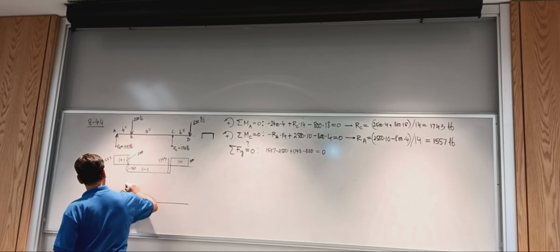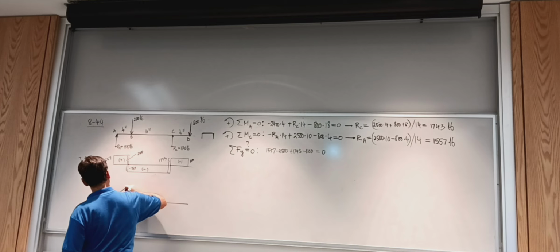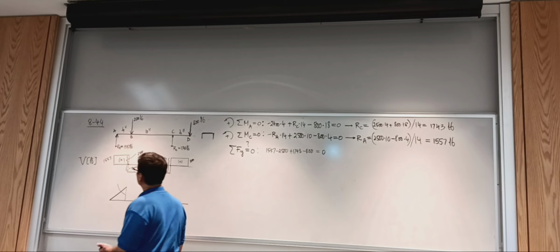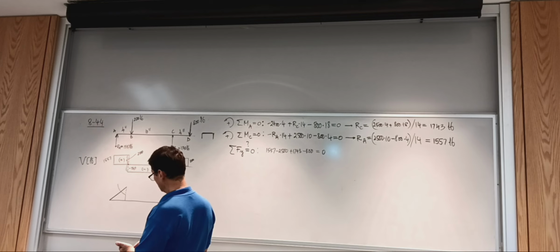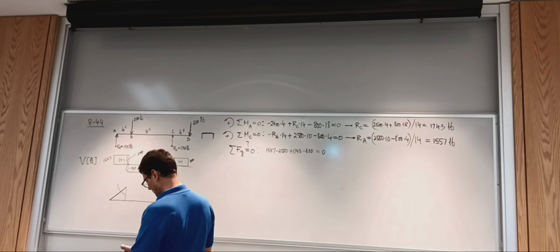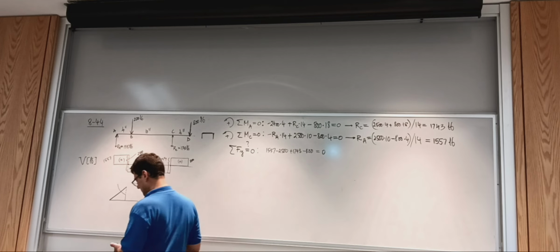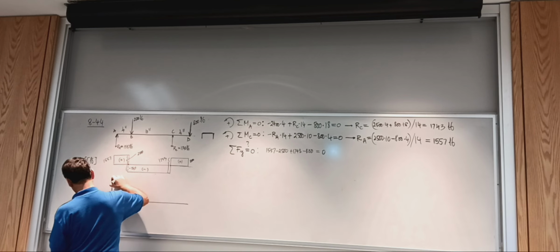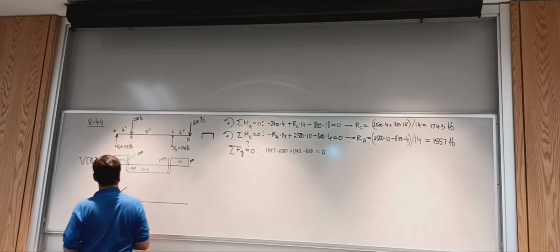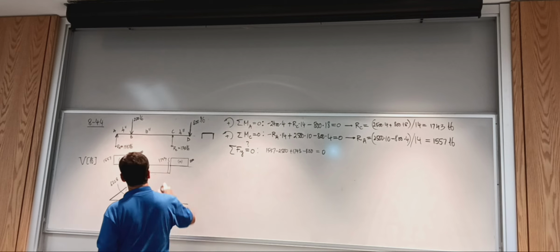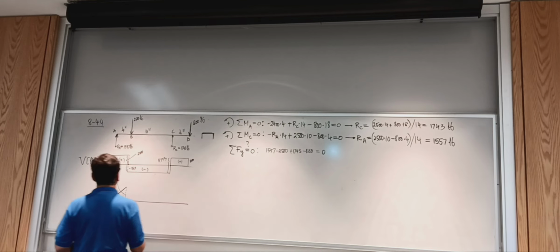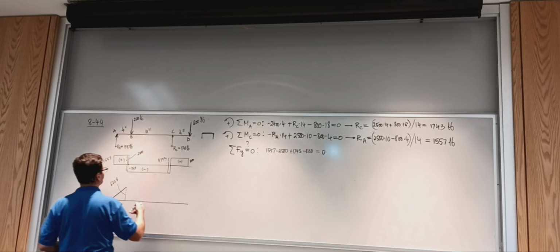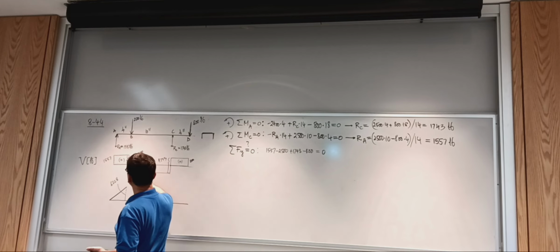So what is the magnitude right before point B? This is going to be the area: 4 inches times 1,557. 1,557 times 4 is 6,228. Okay. And then the slope changes to negative but lesser slope.